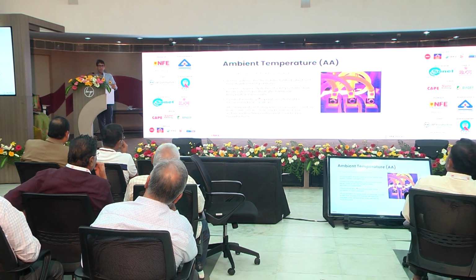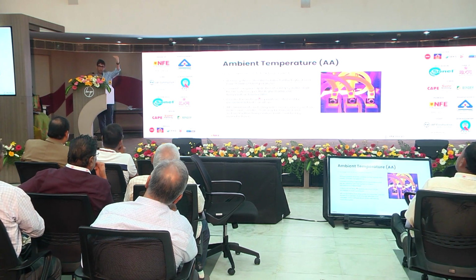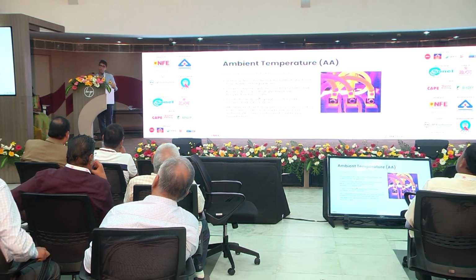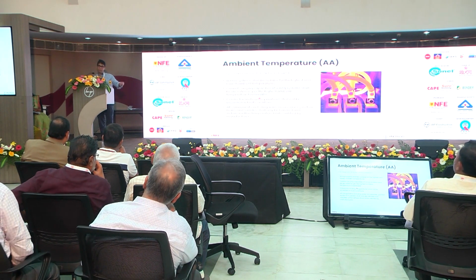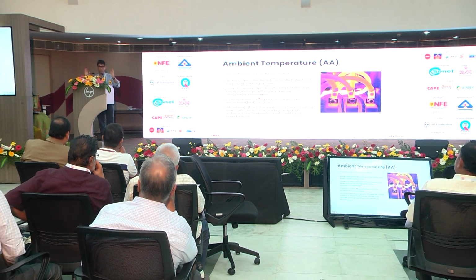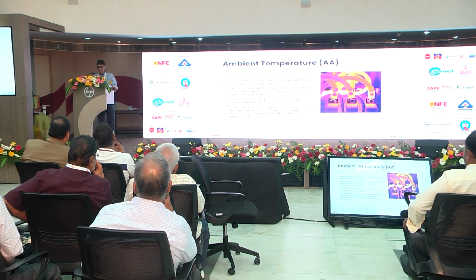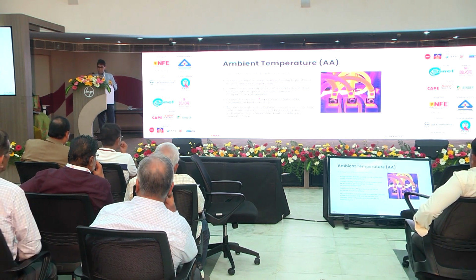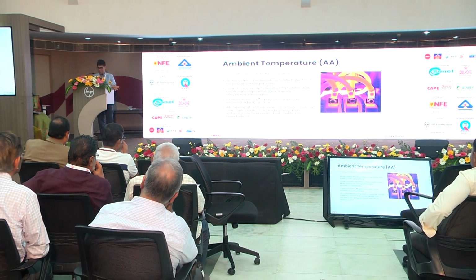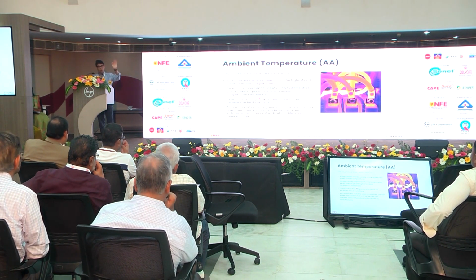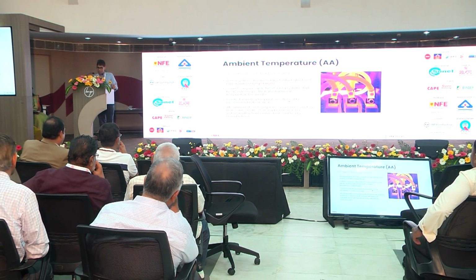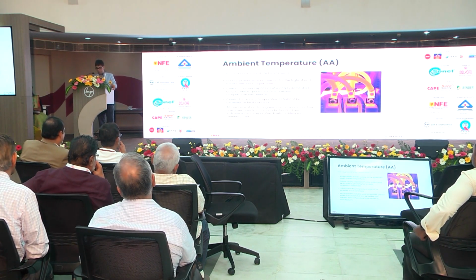It should be derated for the highest temperature possible. So let's say we are doing an installation in an area that can get hot in the summer and can get cold in the winter. You cannot say right now it is 25 degrees, so I'll take the 25-degree current carrying capacity. You need to look at the overall utility. Limiting temperatures are adiabatic. Coming to adiabatics, usually this is 160 degrees Celsius for cable. That is in a fault condition, how hot the cables get. And so we need to ensure that they do not exceed this temperature in a fault condition.